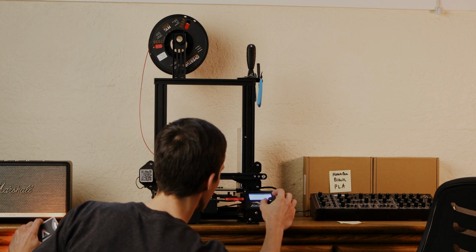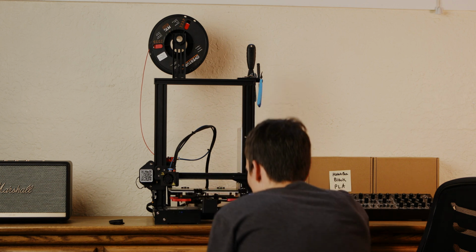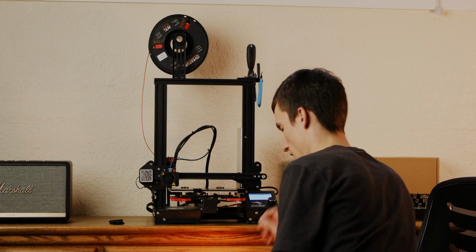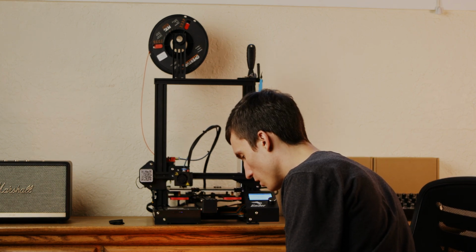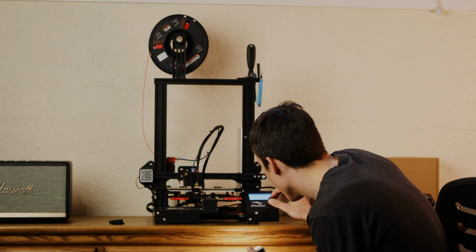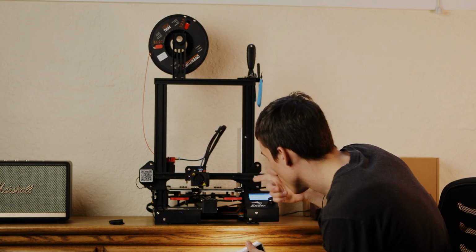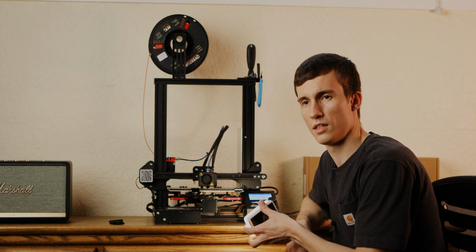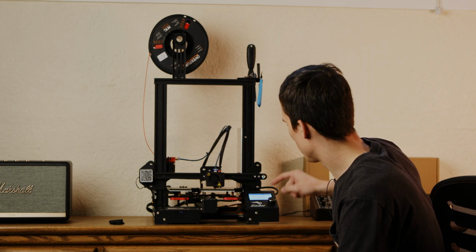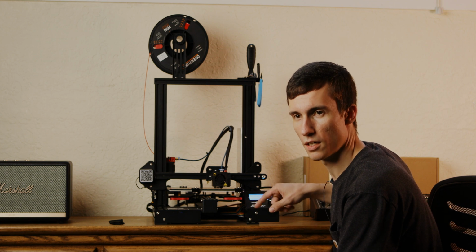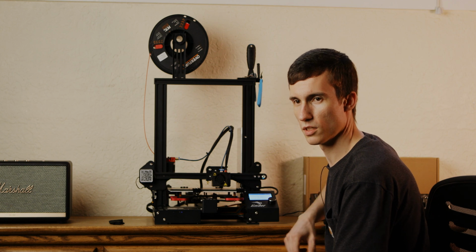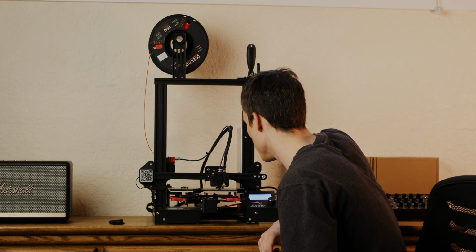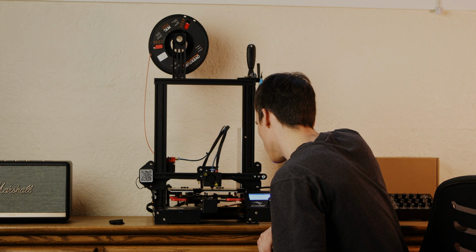tune. Baby step Z. The plastic is going down, which is good. And sometimes what I do is I baby step the Z as it's printing to give it a better adhesion. Yeah, because it was printing a little too high, so I just gave it 2 micro or baby steps down in the Z direction, and that got it to squish the plastic a little bit better on the bed. And it seems like the thickness is even.